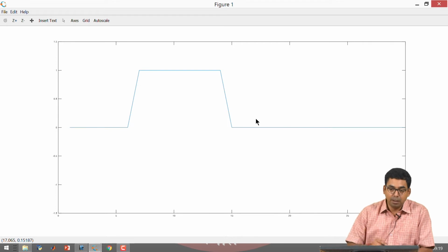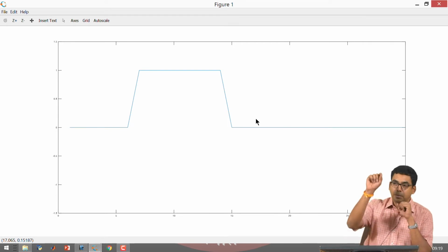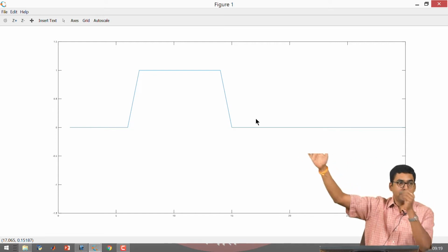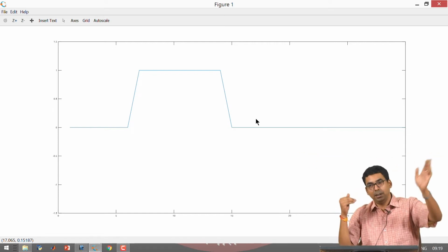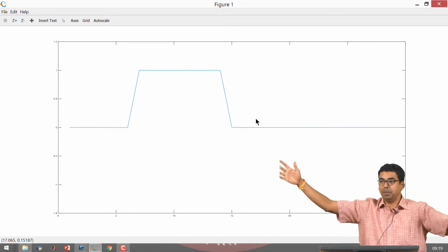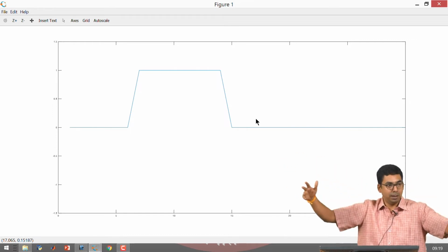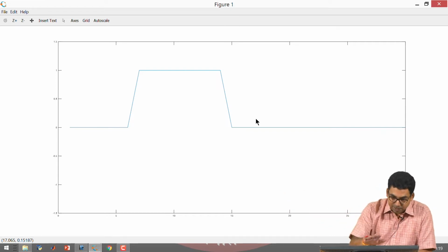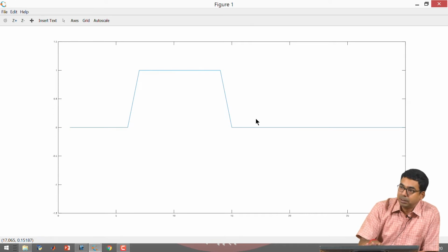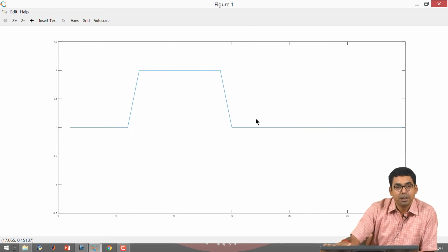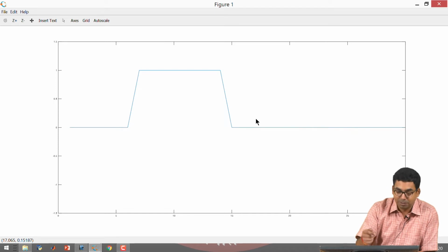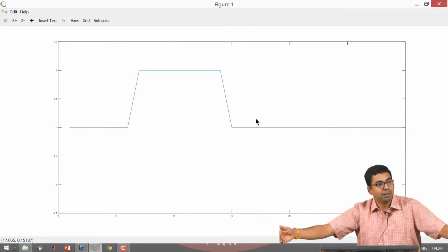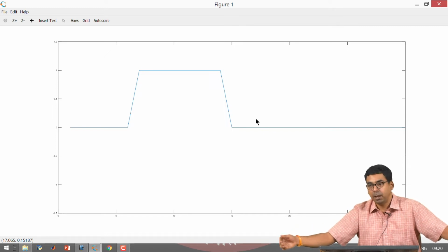First of all, when we began the program, we noticed that from the position there was a voltage wavefront traveling to the right side, there was another voltage wavefront traveling to the left side. They go and hit the boundaries, and depending upon the boundary conditions they get reflected. They can also have sign change in reflection. Due to this, at this instant of time where we have stopped the simulation, the voltage profile across the transmission line looks like this. There is a voltage of 1 volt in some portion, the remaining portion of the transmission line has 0 volts. Okay.